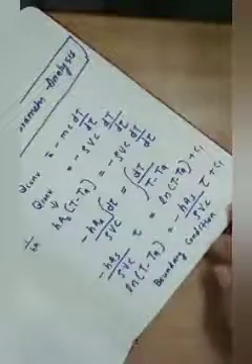This is a transient heat transfer, so the boundary condition must be related to the transient condition. The boundary condition is the initial temperature: T is equal to Ti, where i represents initial temperature, at tau equal to 0. Tau is the time.